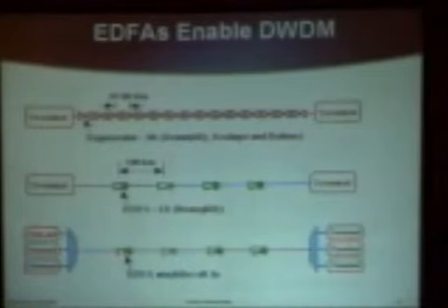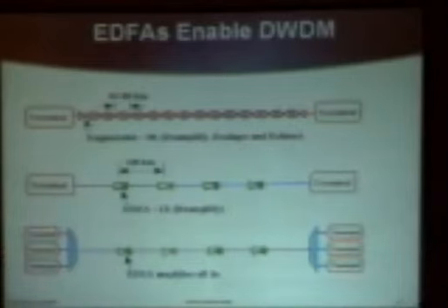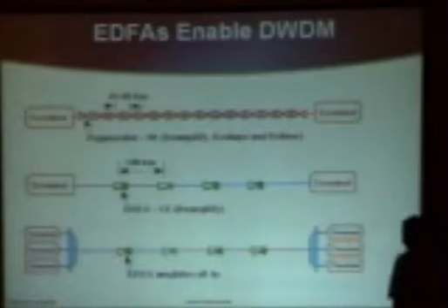The idea was we've already stripped out a lot of the regens, and we put in optical amplifiers. Optical amplifiers can amplify all sorts of signals simultaneously. Let's just multiplex at the optical level many different terminals, each on their own wavelengths, into a pipe and send them down the wire, and the optical amplifier will amplify all of them, and we'll sort them out at the far ends.